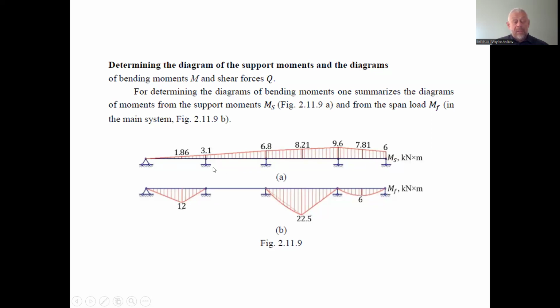And we can make the diagram for the single span of moments of the fictitious load, which gives us the continuous distribution of moments along the whole continuous beam. So the moments in the hinges will be the magnitudes of this one, which was exactly 0. This is a hinge, not an assumed hinge, but it was from the first of the assigned system.